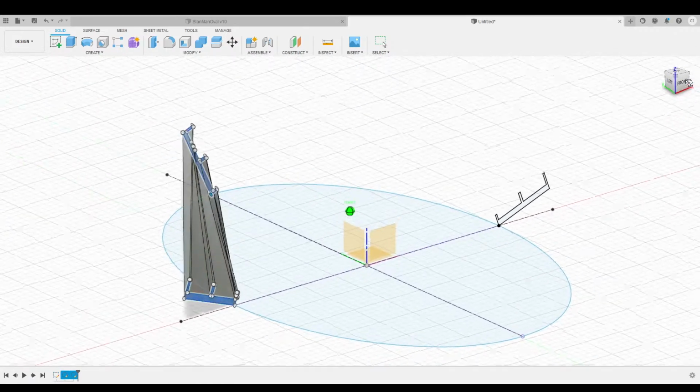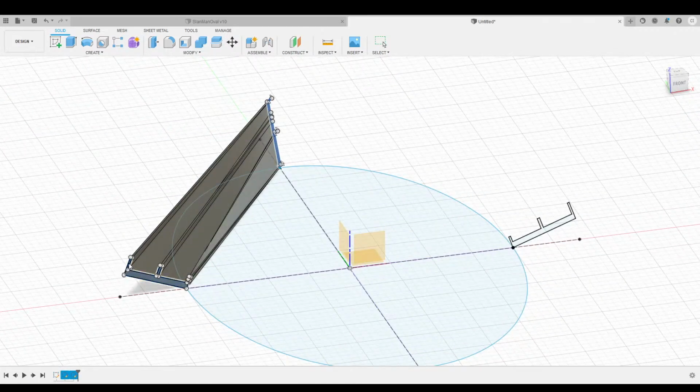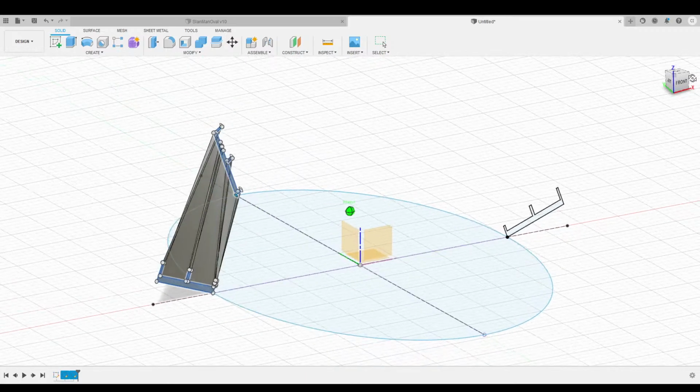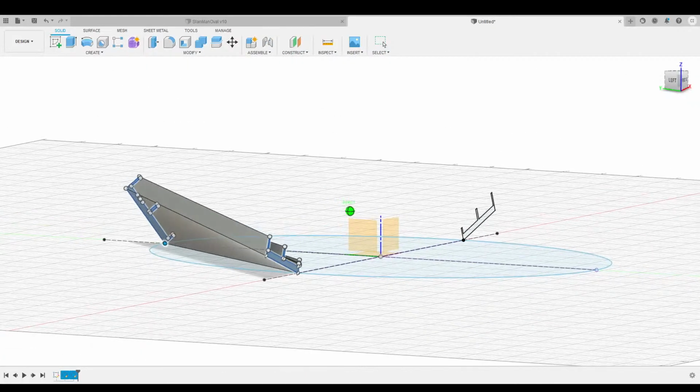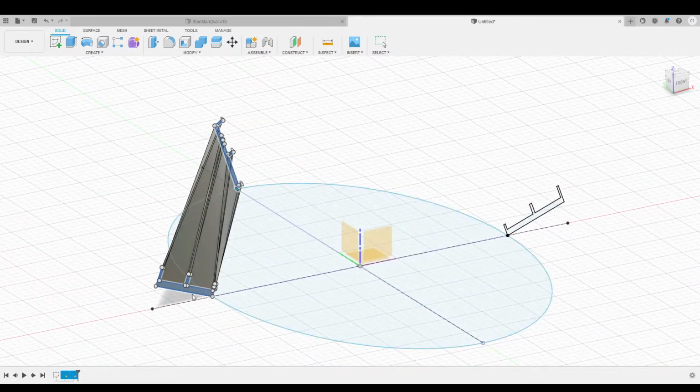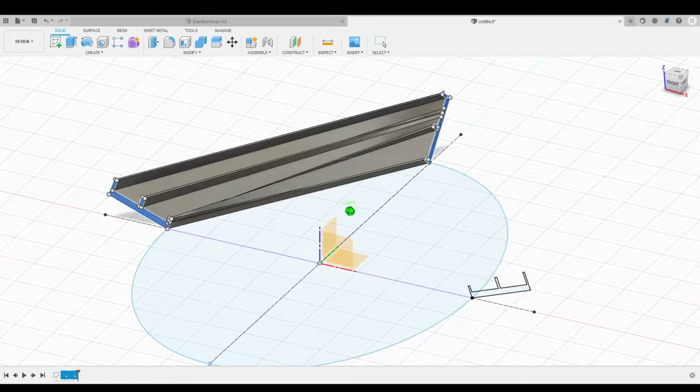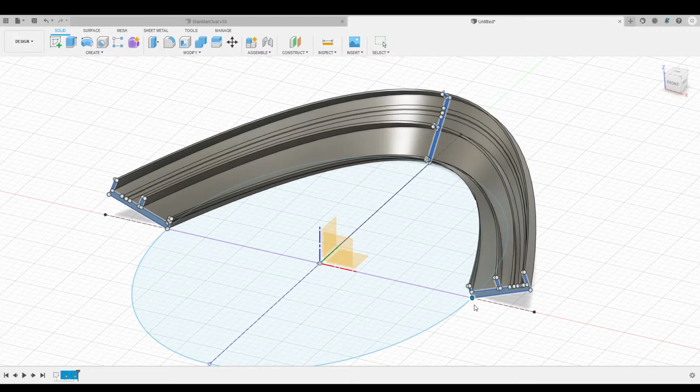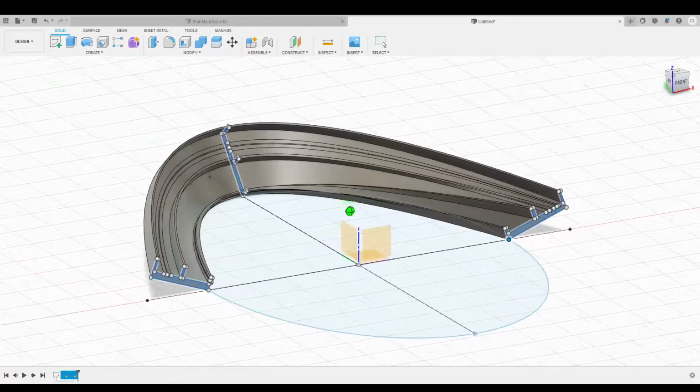This doesn't happen when the turns and the angles of the shapes of the profiles that you're trying to map together are not as extreme. I'm sure somebody could probably write something in Fusion to actually do a little math to see that these are actually the same shape and maybe map them appropriately, but that's beyond the scope of this. That'd be something for Fusion people to actually do. So ideally, right, we'd pick that profile, profile 2, pick profile 3. It's trying really hard, bless its heart.